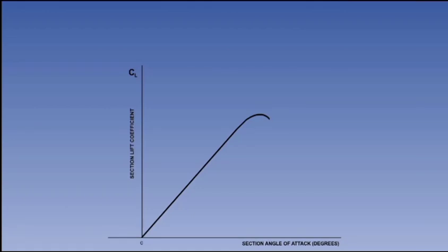A high CL maximum is only one of the requirements for an airfoil section, but the main point is that it gives a minimum flight speed. With the low stall speed, VS, comes the penalty of a low efficient cruise speed because of the excessive drag generated.